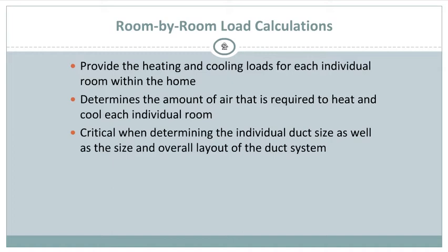Again, this is critical because you want to determine the duct system and the duct size to meet your furnace system. If your furnace system doesn't meet your duct size, you're going to get complaints like, oh, the back room's always cold, no matter how high you have the thermostat. So you've got to make sure that your duct system matches your furnace and so on. And we'll talk about different types of furnaces as we go along. But again, this is critical in determining your duct size and your heating loads, because you need to determine your furnace size and your duct size.